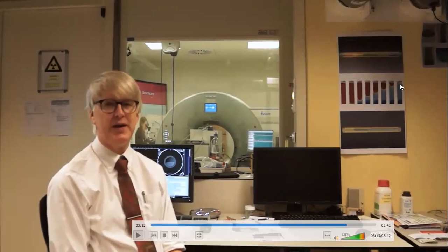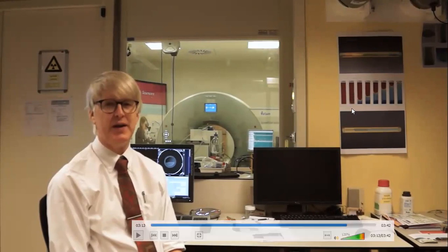Okay. Where is the bubble point pressure? Well, this is the undersaturated condition when it is all oil. And then what you do is drop the pressure. When you drop the pressure, the first bubble of gas comes out, which probably is here. And then as you further drop the pressure, the gas forms a separate phase. So here you see that the gas has separate phases, but here only a single phase, all oil. And here you see under low pressure it all becomes gas, and the oil is at small pressures.